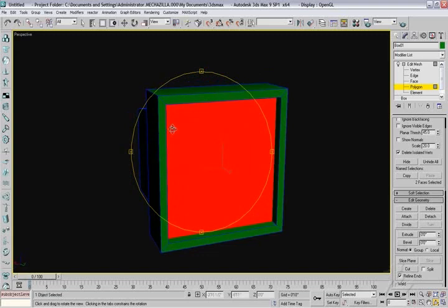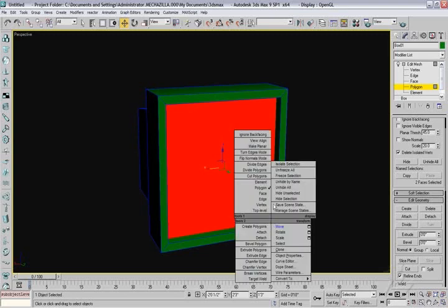However, we do have some visible edges when we extruded these faces. When Max creates new geometry, new polygons like this, it will create visible edges along its seams. Wherever you stop and let go of your button, it creates those new edges and they are visible. Now, just to show you and remind you that everything is still made up of triangles, we want to change up our model so that we can see those invisible triangles. So go ahead and right click in your perspective viewport, and then right click again with your model selected, and this should bring up your quad menu.